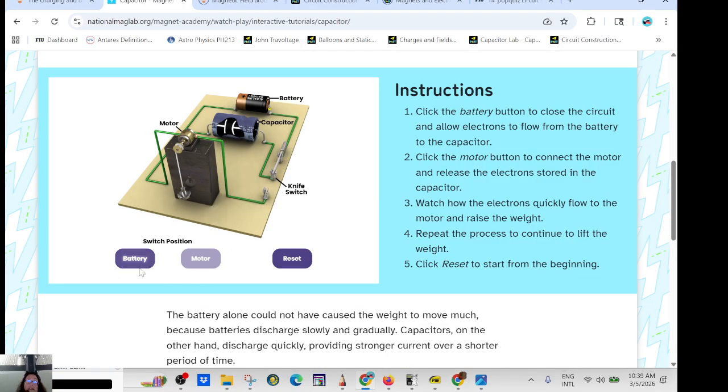But here you can see that at the beginning, you're going to have a lot of current. The capacitor is not stopping the current. And when you wait long enough, there is no more current flowing. If there is no more current, there is no voltage drop across the load, and the capacitor is holding the charge, and the voltage across the capacitor will be equal to the voltage across the battery.